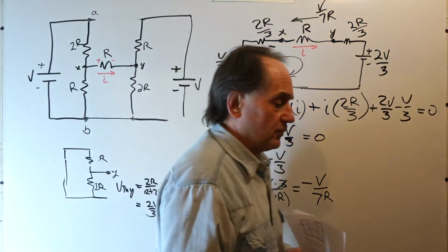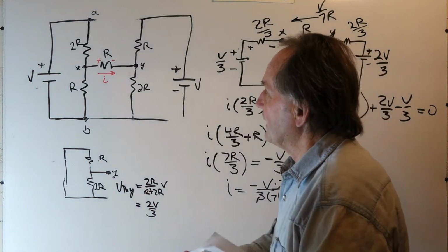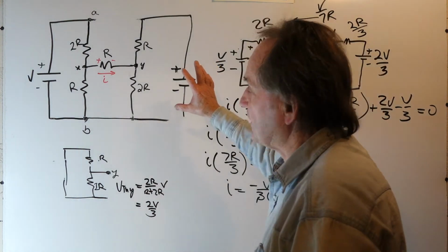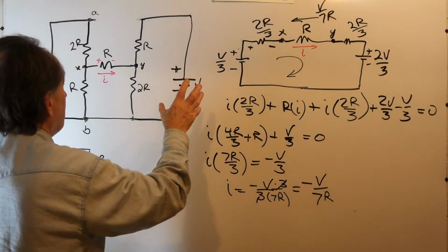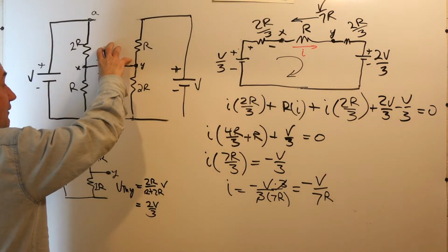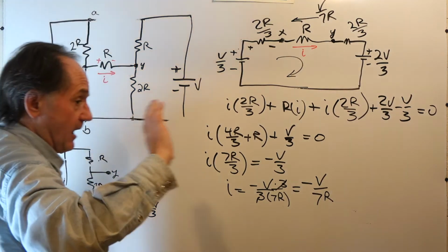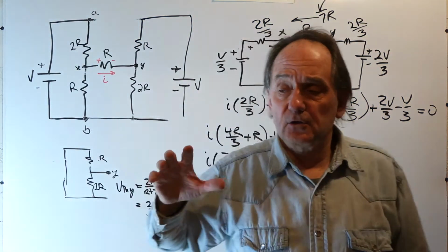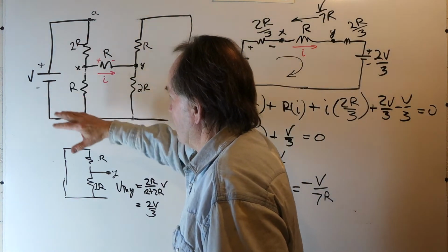Now, when you do these substitutions and accomplish network reduction using Thevenin equivalent, the only information that you can get related to the network is between the terminals, outside the Thevenin network. You lose the network information during the transformation.